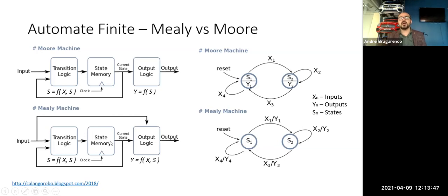We are controlling the network data flow, and we are always checking the CRC to see if the packet and the protocol are followed. If the protocol is not followed, then change the state memory to what? To the fail state, and don't provide the input to the output. But if everything is okay, the input is provided to the output. This is just an example.